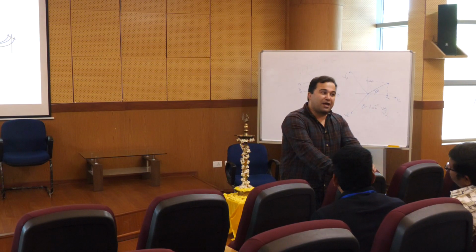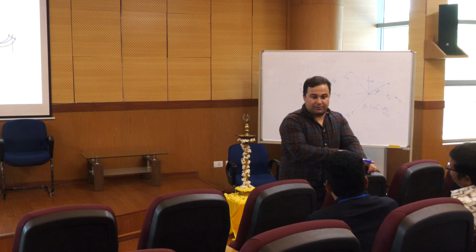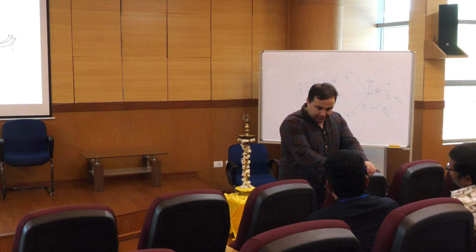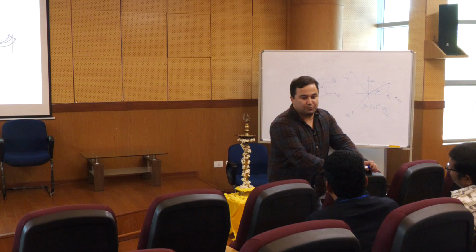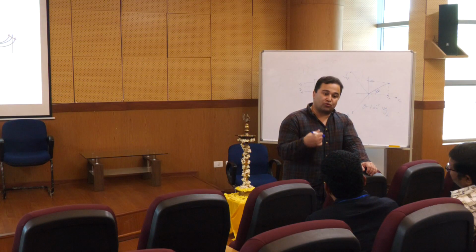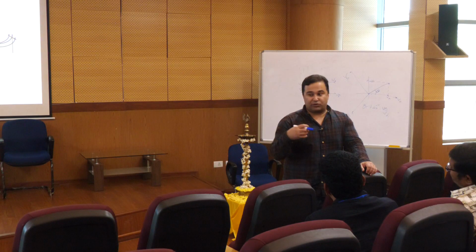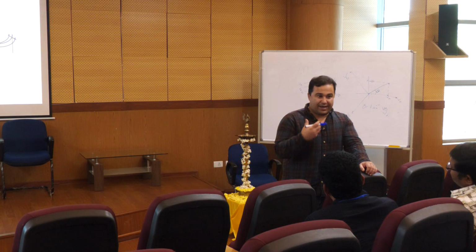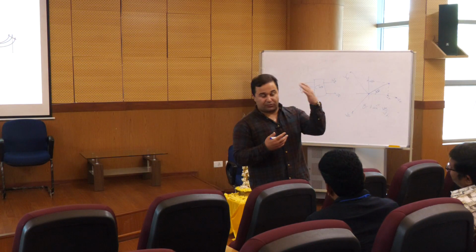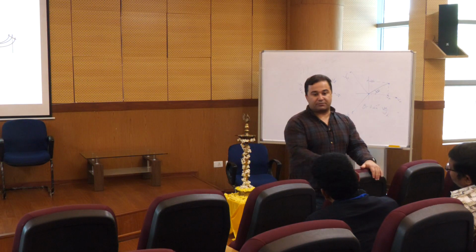Yes. So let me answer your question with a question. Can you supply your load by this PV or not? You can. Okay, it's fine. Because, I mean, it comes back to the control aspect. If your controller is designed in a way that your converter can act as a voltage source, it means that it doesn't need to be connected to the grid and can provide the energy for the load. It is a microgrid. Okay.